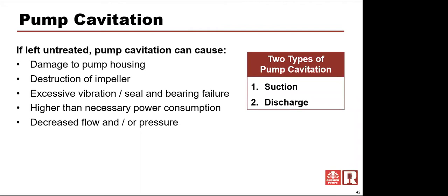Well, there's no solids going through it, assuming there's no solids in the liquid. It's that formation and collapse of the vapor bubble that's creating that sound. It sounds like you're pumping gravel.